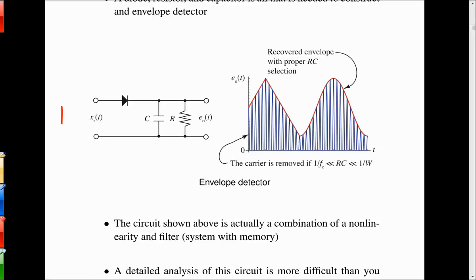When I was in school, and I was first working in industry at Motorola in Scottsdale, Arizona, my big baby, so to speak, was an AGC amplifier for pulses that came from a photomultiplier tube on this Lasercom comm link. So not only did I have to have a wideband amplifier that could process these 200 picosecond wide pulses, I had to regulate that gain to be a constant value, so I had to build this AGC circuit. And it was fairly challenging for me. It was definitely an electronic circuit design type problem.